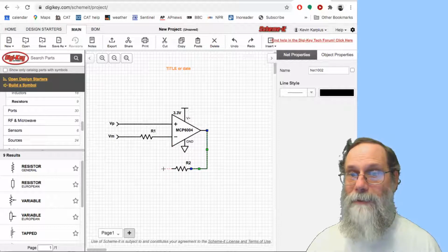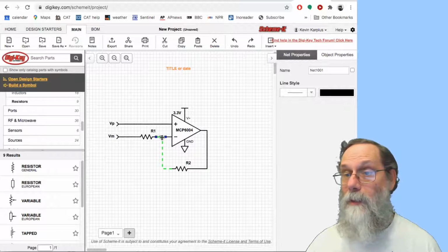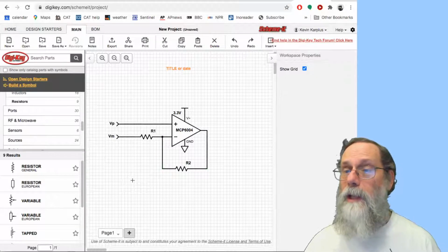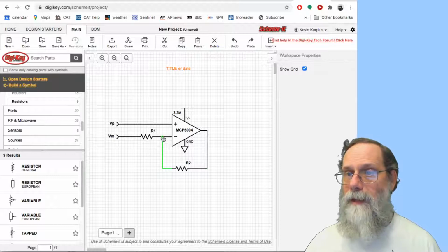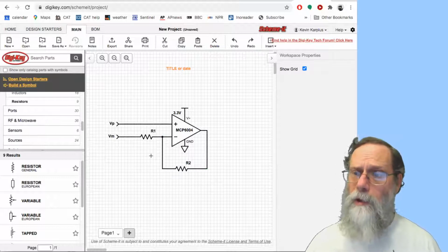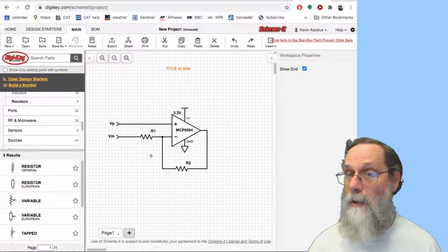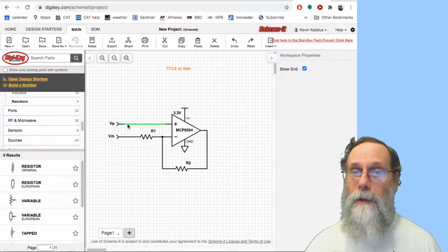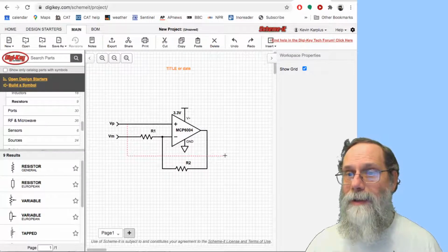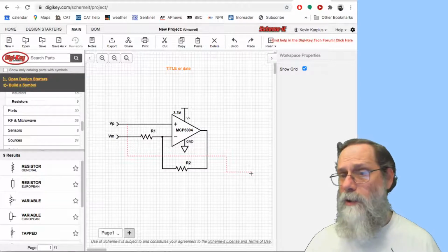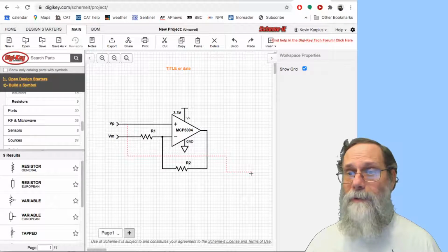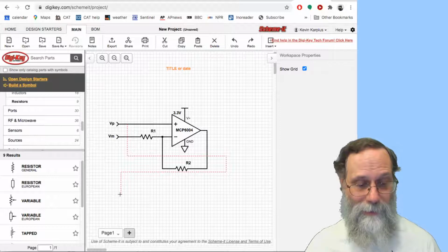I have to do the same thing of click, and when I hit this wire, notice it lights up the wire. I click there, and if you look at what it's done here, it's put a connection dot there. See that circular dot? That's indicating these wires are connected. They're not just running past each other. I mean, I could have taken something from here and run it over to here, and it crosses those other lines without making a connection. And now, because I haven't got anything over here to connect to, it's not something that I can do.